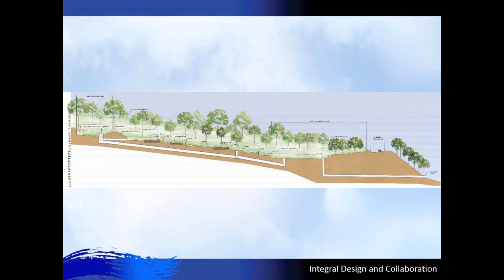Yeah, and at first I had heartburn with this underground pipe, but really what we were trying to do with this project is run 22 cubic feet per second through the above ground features for a water quality benefit. And then once we exceeded that, the additional flow goes through the pipe. But as you can see, that pipe on the left side comes to an end and actually surfaces in a pond.